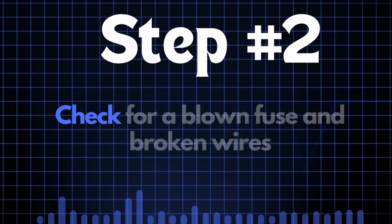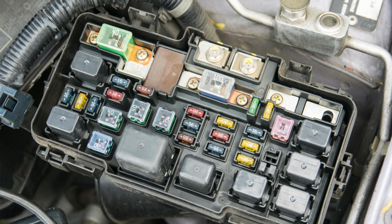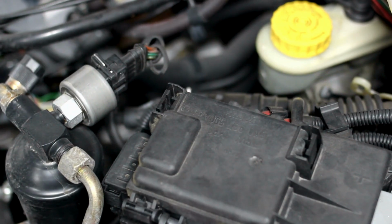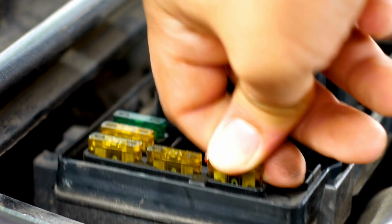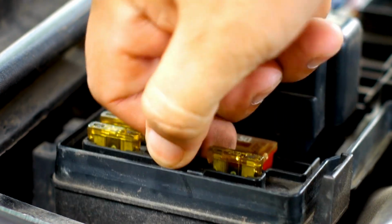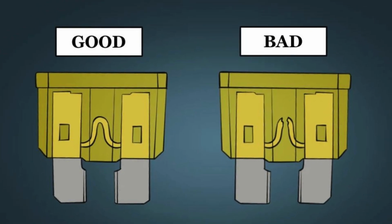Step 2. Check for a blown fuse and broken wires. First, locate your car's fuse box. You'll need to find the specific fuse that controls the oxygen sensor heater circuit. To do that, check the diagram on the back of the fuse box cover. It'll tell you which fuse is the one you're looking for. Once you've found the fuse, inspect it closely. If the fuse link is broken, it'll need to be replaced.